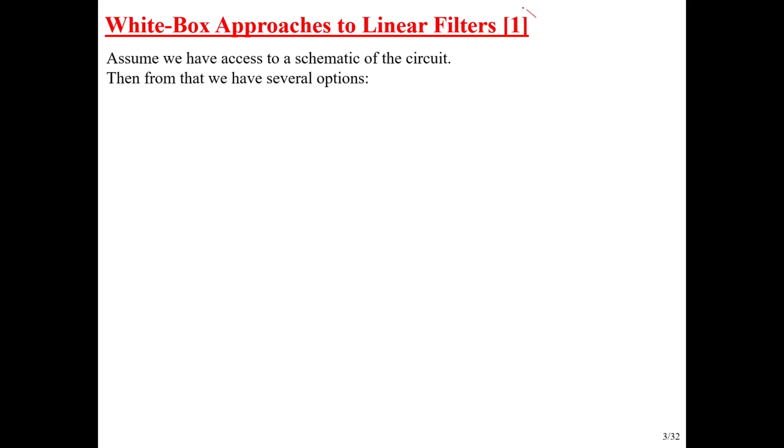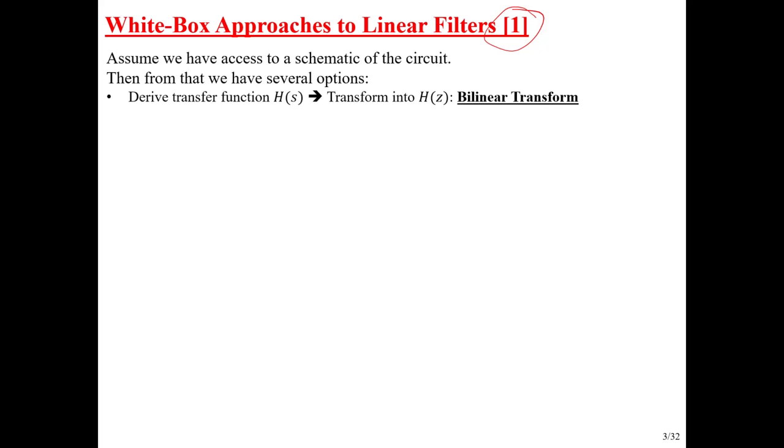Okay, so here's our white box approach. This is based upon David Yeh's ideas in his paper. White box says we've got access to the schematic. And from there, we've got some options. We're talking about linear filters, so we could just derive the transfer function and then use the bilinear transform to transform it into a discrete-time filter, and then we know how to implement that.